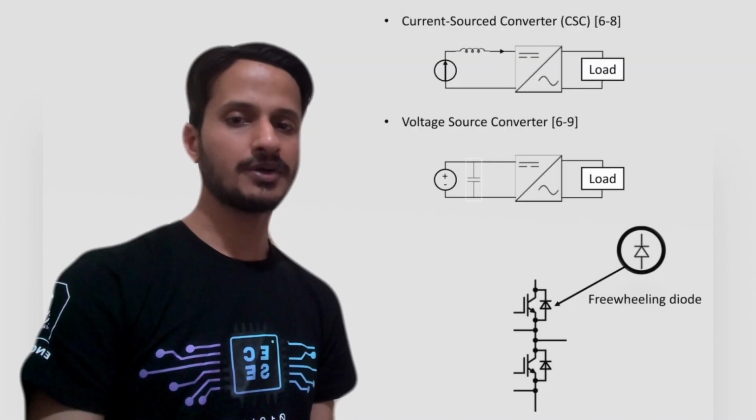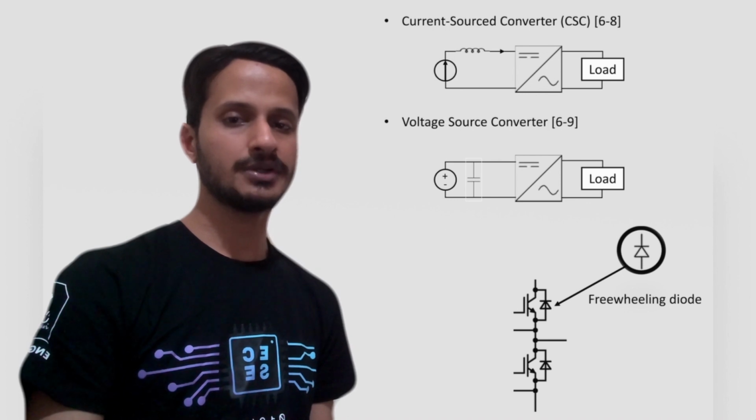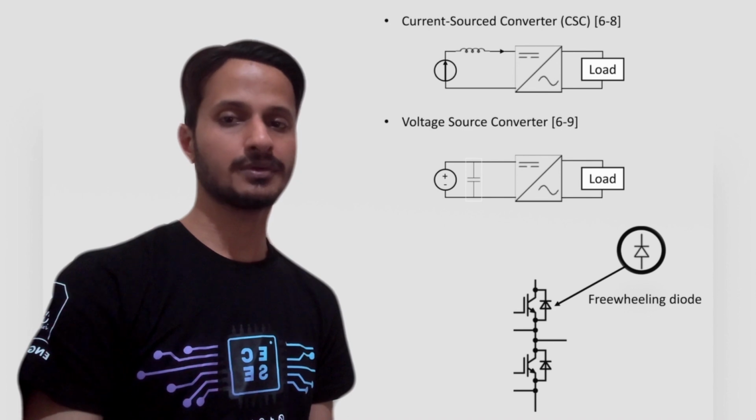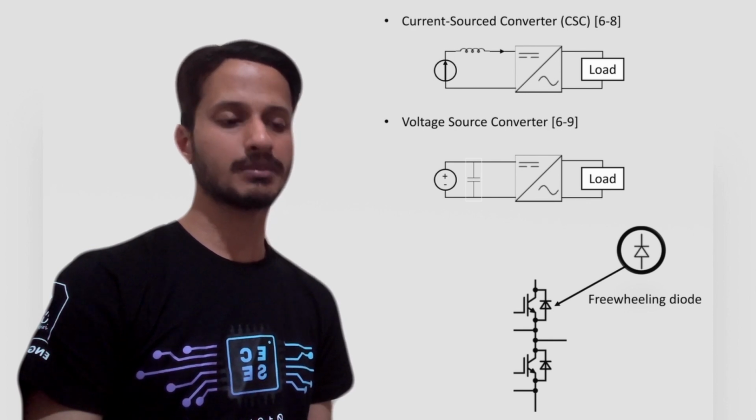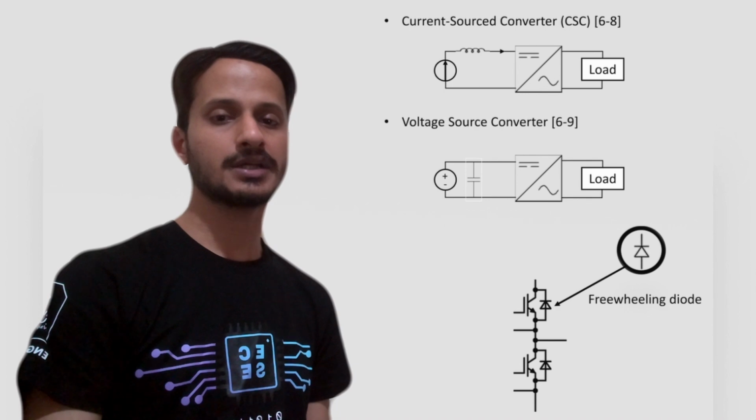There are two types of power converters, current source converter and voltage source converter. Current source converters are line commutated as they use old thyristor technology, so they only turn off on zero crossings. Therefore, it depends on AC system and requires large reactive powers to work. Further, it has no asynchronous system connection supported and no multi-terminal system capability. On the other hand, voltage source converters are self-commutated as they use modern switching technology, and provide independent active and reactive power control. They can support asynchronous system connection and can work with forthcoming multi-terminal DC system.